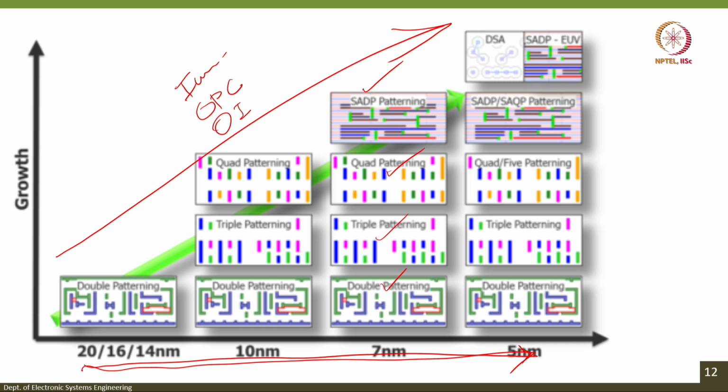I wanted to make you realize how we can reach from 50. In the first lecture I tried to explain how we can reach 50-60 nanometer. In this class I tried to explain how we can reach from 50 nanometer to 2 to 5 nanometer. But still, as I mentioned, people are going ahead and making devices with 2 nanometer, 1.5 nanometer. How is it possible? If time permits we will see that. Otherwise, there is something called EUV, and I would encourage you to check extreme UV lithography and E-beam lithography. Combinations of several resolution enhancement techniques come together to get your final device.